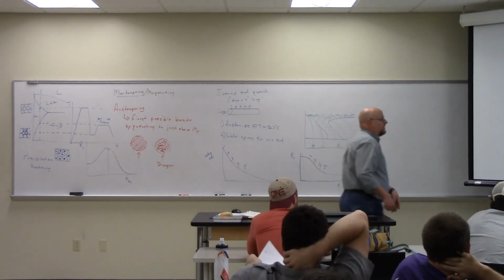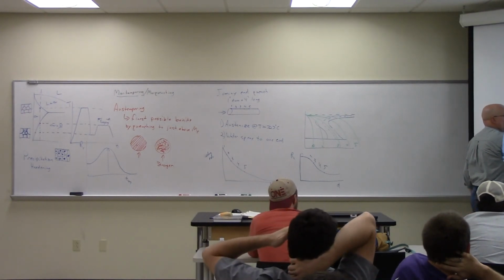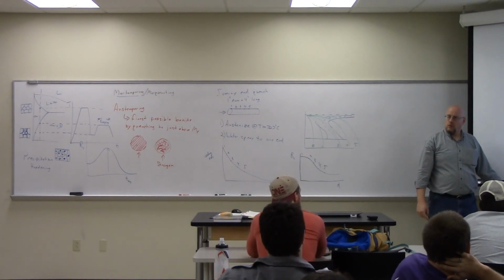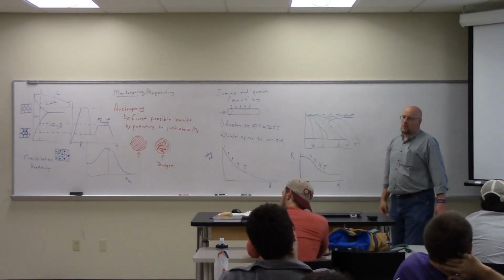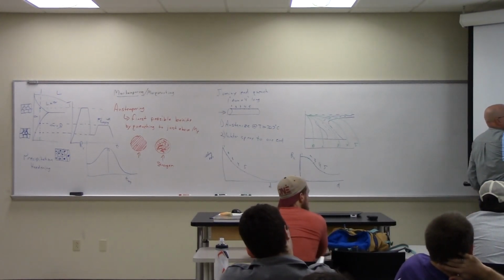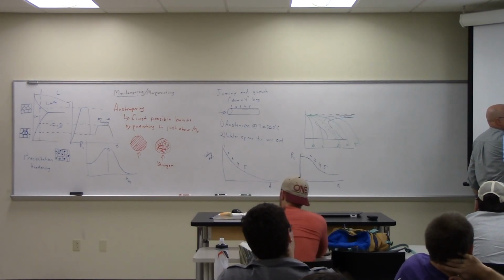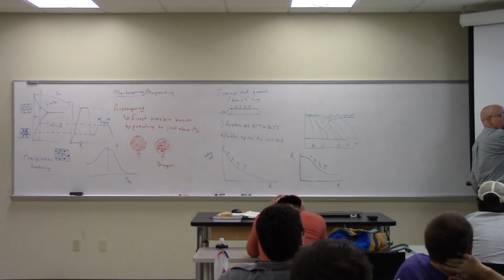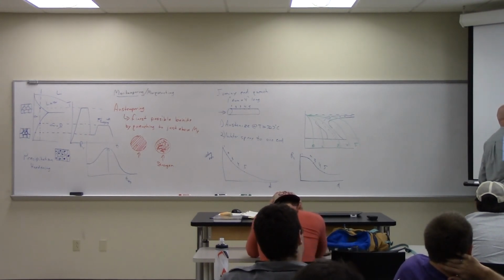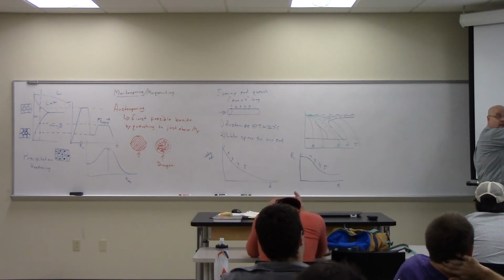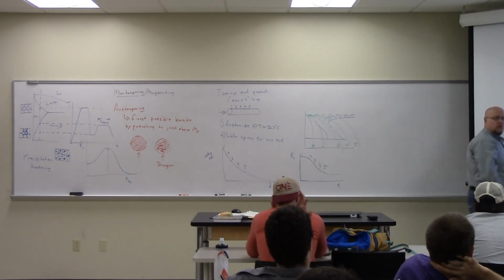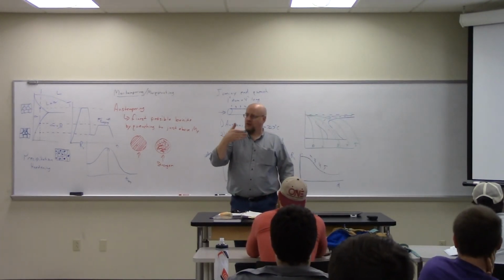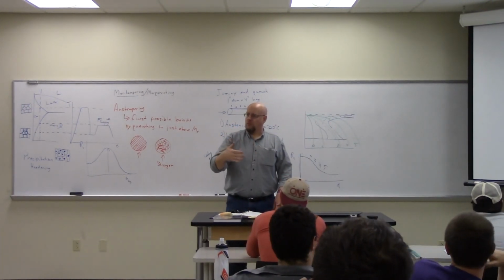It's the equivalent of basically this process. Don't you go from where it first enters though? Yeah, so what I'm saying is, if you go like this. Oh, because it enters at some almost coarse pearlite. Right, it enters here and it hits 50% there, so essentially we've got this, but only 50% of it. And then the rest of it's down here at martensite. Okay. So you basically track the furthest intrusion that you get for your percent transformation.